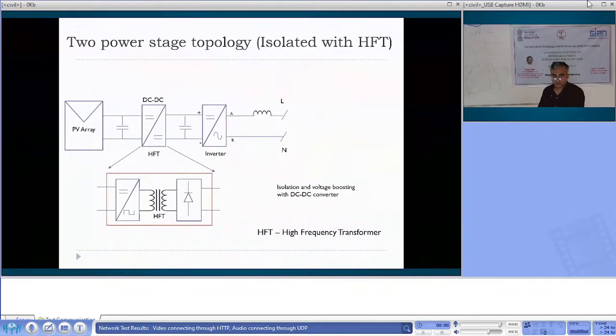How common are these configurations? These are very common actually. To make the inverter very compact, we use this. Very much economic because it takes very less space as compared to a low frequency transformer. Low frequency is a very huge transformer, very bulky. Weight is high, efficiency also reduced. It is economical, maybe complex, but economical.